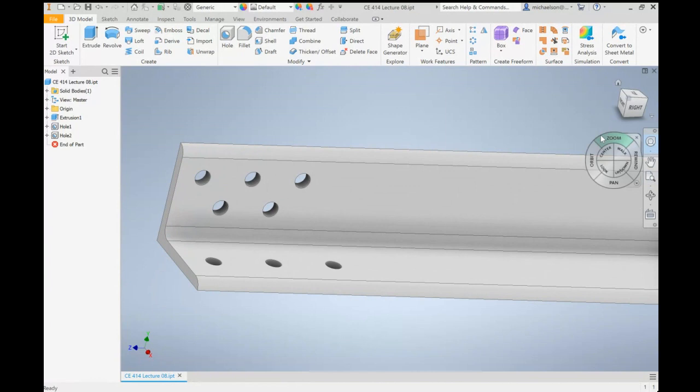I'm going to use the compass as kind of like a laser pointer. This is the gross section all the way out here, and the net section is going to be somewhere in this vicinity. The first thing you have to do is identify the lead line of bolts. The lead line of bolts are all of these bolts here, those three, the ones closest to the gross section of the body.